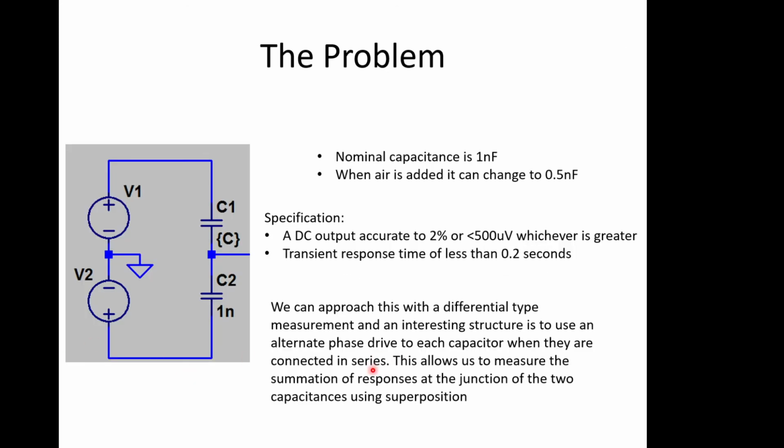So if we draw that as a little circuit, our fundamental sensing problem becomes, here's our reference capacitor, and here's our sensing capacitor, which would have the fuel flowing through it, and if there was air, the value of this capacitance would change. This one's always got guaranteed fuel in it. That itself is a bit of a problem to define, but let's assume we've cracked that one, so we've got a little sample of fuel in here. And then if we measure the difference in capacitance between these two, we can work out what's going on.